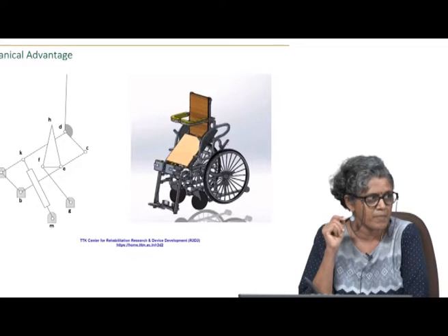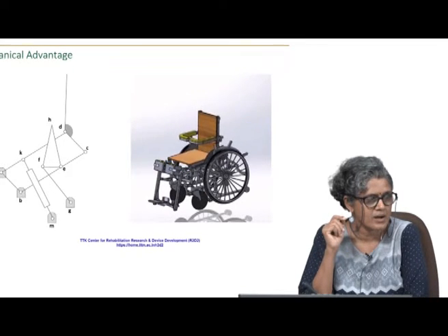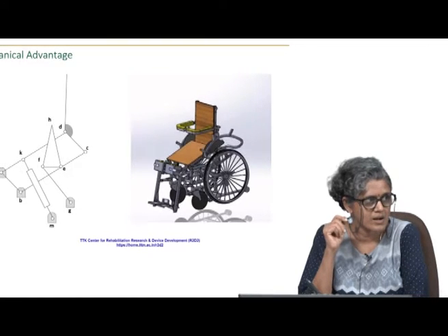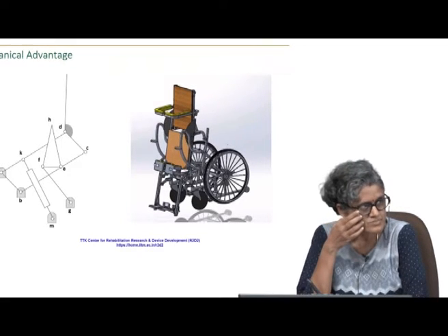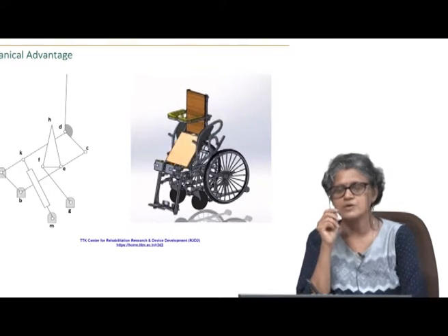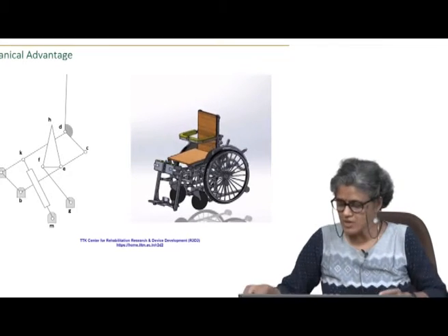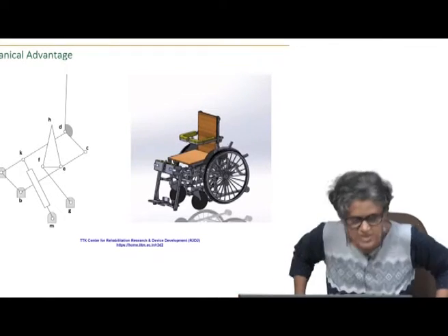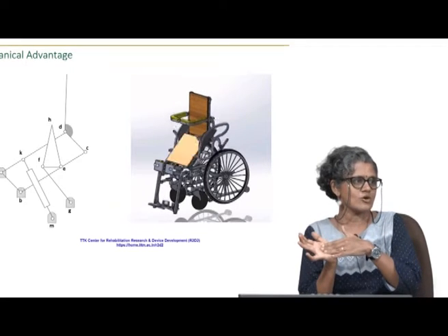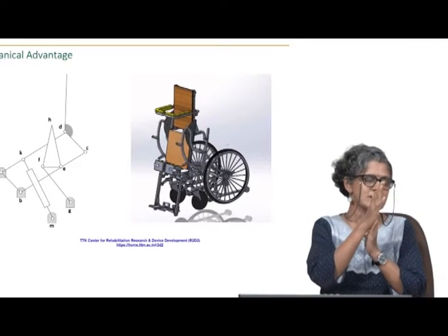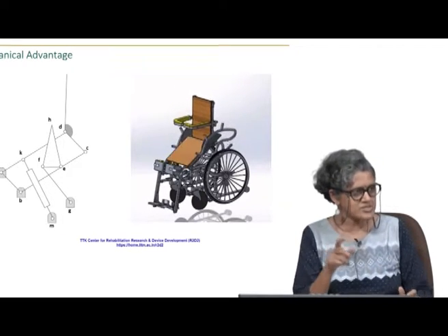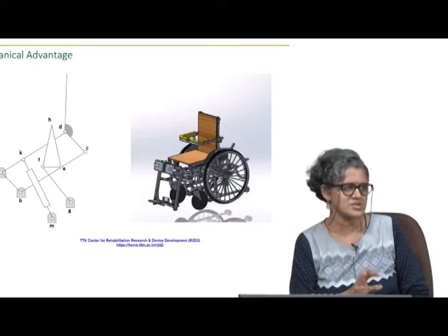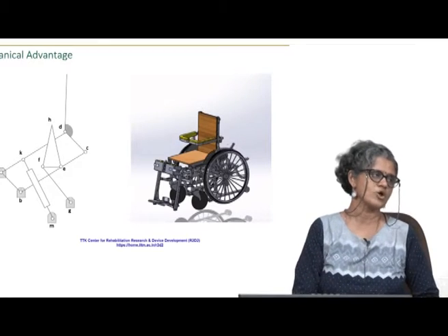Yes. In addition to that, ma'am, in the video, irrespective of how much ever the person lifted, the mechanism blocked there, and this happened while going up as well as going down. So, does that imply there is a worm gear that has been put in? No, no. The locking mechanism is by ensuring that in the sitting position it is at a toggle position, and the standing position also you come to a toggle position, and then you have a positive lock, but the toggle position is what is locking the mechanism.